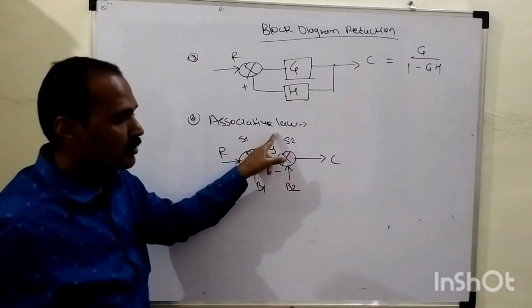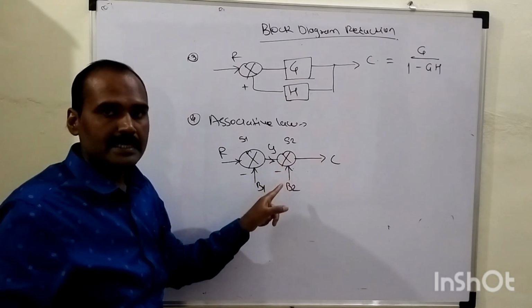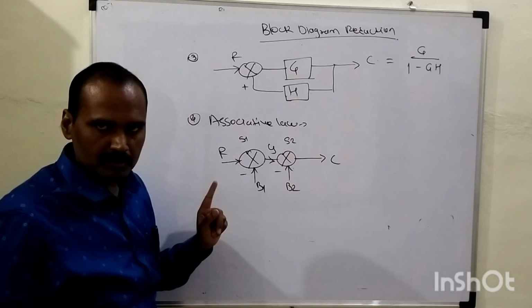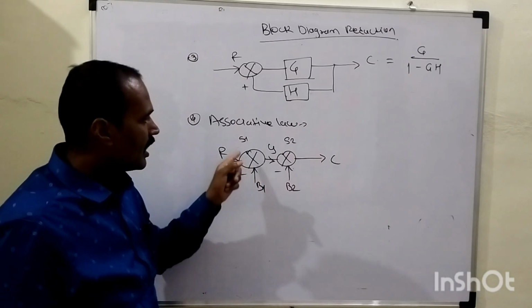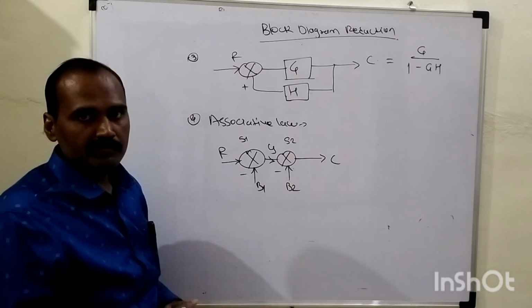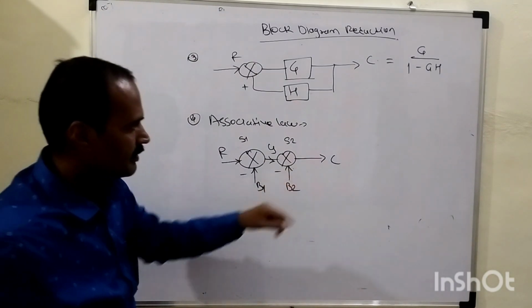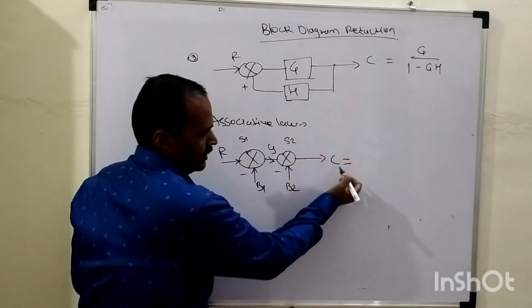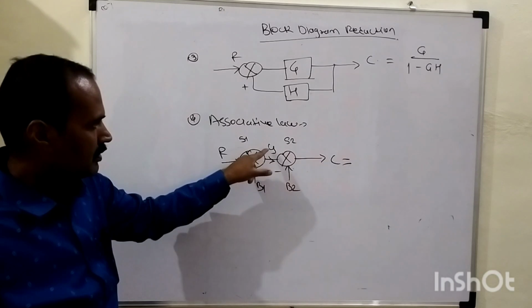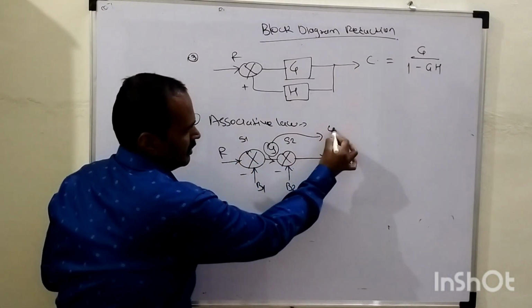So this associative law says that whenever n number of summing points are connected in series form, meaning we don't have any subsequent term connected in between these two summing points, according to our convenience we can change the order of these summing points, right? To understand this rule, let us quickly declare what this C stands for here. To generate this C, first of all we need to determine this Y, that is nothing but the output of the first summing point.